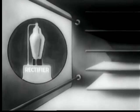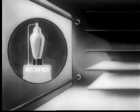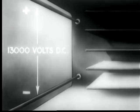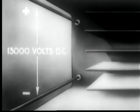The rectifying property of electronic tubes is used to apply a potential of 13,000 volts DC to tungsten wires and 6,500 volts DC to collector plates. As incoming air passes through the field of these wires, each particle of dirt receives a positive electrostatic charge.